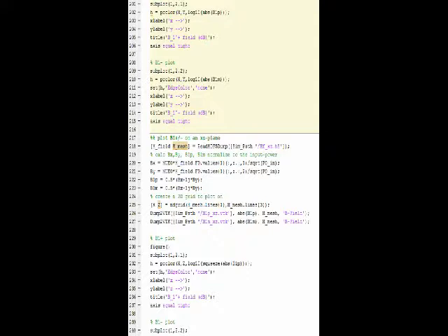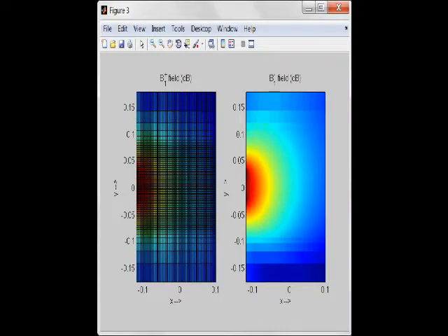To create a 2D grid to plot on, we're using the function NDGrid, followed by the B1 plus plot and the B1 minus plot using the pcolor plot function. As shown in figure 3, we have the B1 plus field and B1 minus field. In the B1 plus field picture, we have all the meshes showing up. To simplify the problem, we're just going to look at the B1 minus field. The B1 plus field is exactly the same as the B1 minus field. It has tiny differences, but we cannot see them by eye.